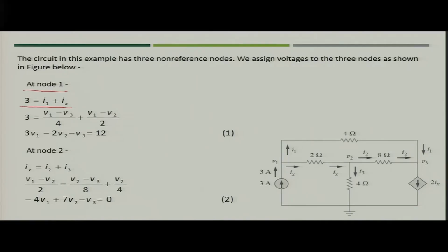Now, you have written this in terms of current, convert it in terms of voltage. So, what will you do? You have assigned the node voltages as V1, V2 and V3. That means you need 3 equations to solve, because you now have 3 unknowns V1, V2 and V3. So, when you write current I1 in terms of the voltages, what can you write?